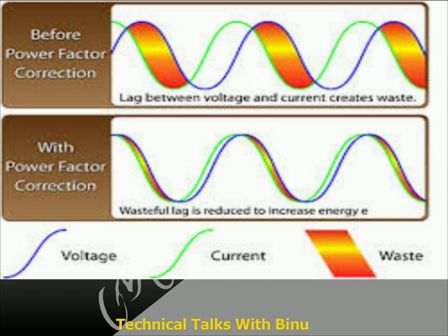Actually, what a capacitor does is, it will store charge from the system and will deliver the current as required when the inductive loads are utilizing the currents for magnetization. Now, most modern controllers available in the market will monitor the power factor of the system and enable automatic switching on and switching off of the capacitors as required. Also, these controllers are capable of monitoring the charge on the capacitors.